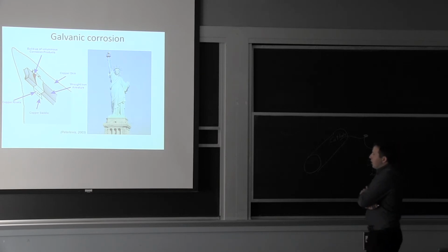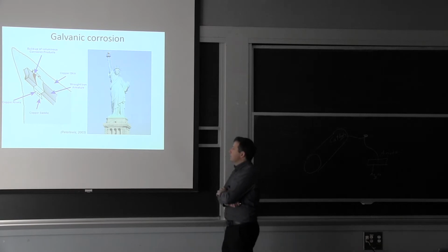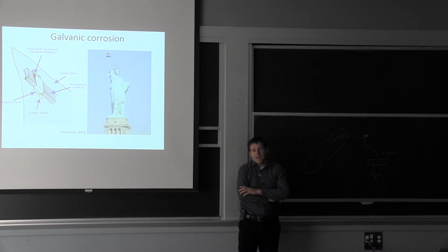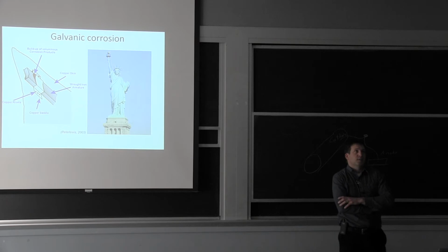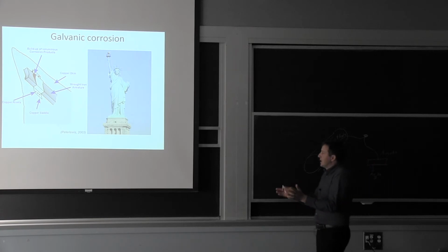When you see wrought iron, it's essentially before we started making steel. So it's not cast iron, but it is essentially a steel, but with a lot of inclusions, and it doesn't really have carbon as a strengthening factor. So it's a very low strength steel, if you will, and it's very laminar the way it's made. It was used in the U.S. in the 1800s, all the way almost to 1900, before we started really making steel. Again, the advantage is it does have the ductility, but it's subjected to laminar tearing and all sorts of things.